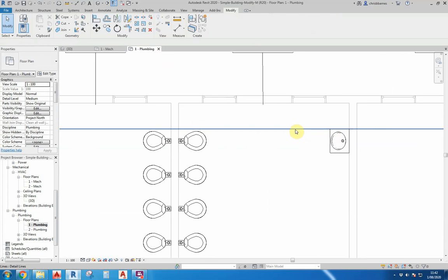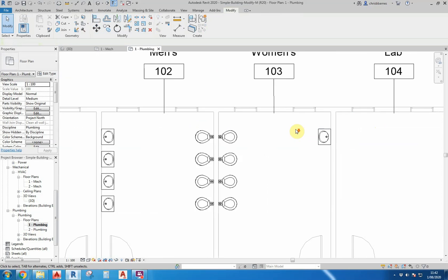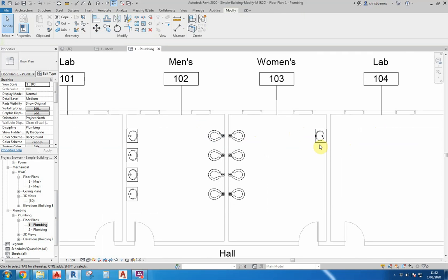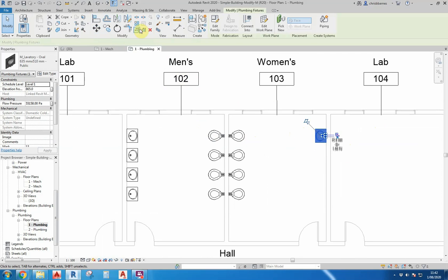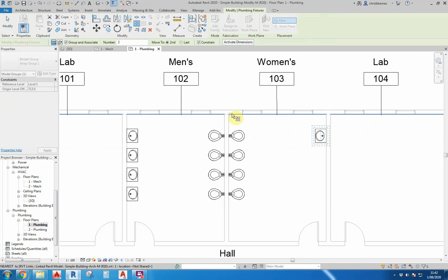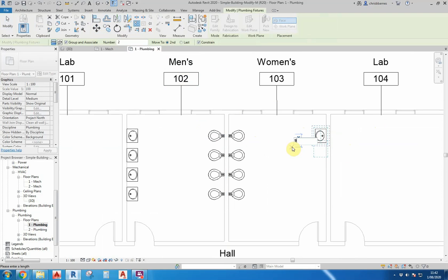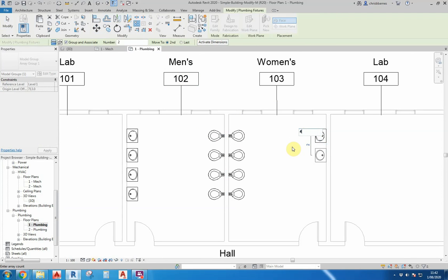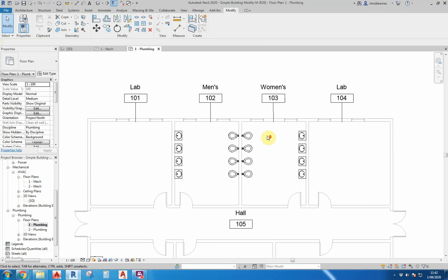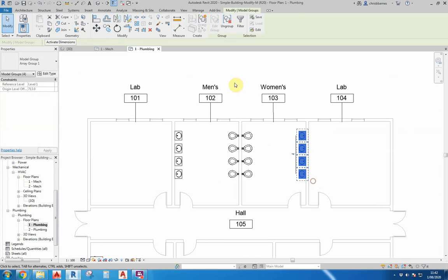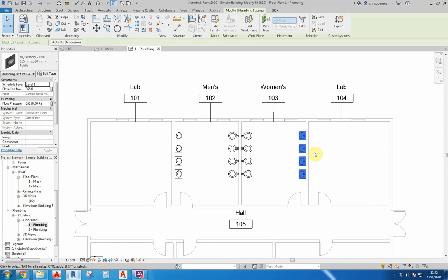Any of these temporary lines that you draw, you can delete those afterwards, otherwise you'll end up having a load of lines everywhere that you don't necessarily need. So linear array, 900, 4 of them. And there we have those particular items. Again, if you ungroup them, then you've got control over how they move.